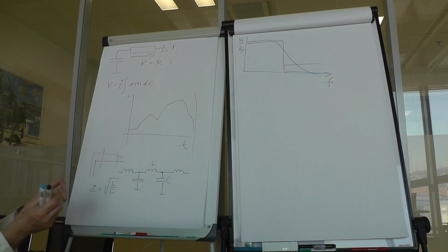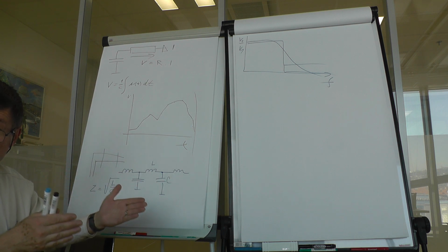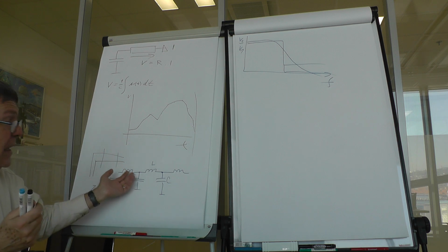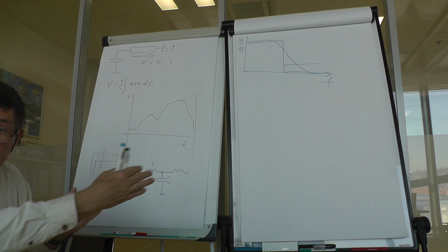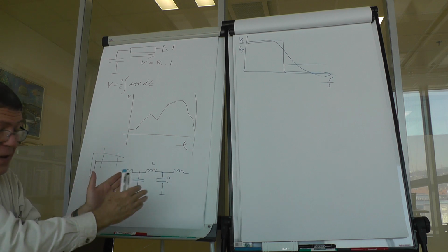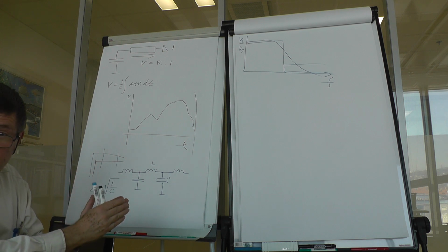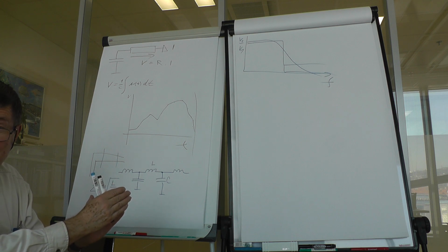And now this is the tricky point. For a microstrip line, for a line on a printed board circuit, this might mean that you, for example, include 100 sections. Because you have to break the transmission line into pieces that are really differential when compared to wavelength.